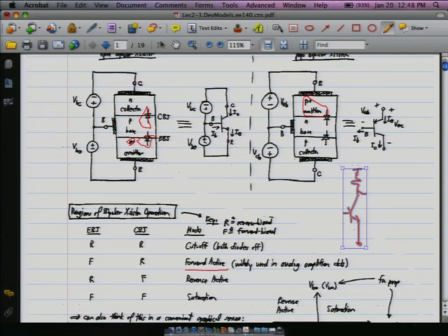And the other mode is reverse active. So basically, it's just flipped from forward active, of course. You would think that if you flip the device, you get basically the same behavior, just in the other direction. But actually, because of the doping, here we see that the emitter is heavily doped and the collector is lightly doped, what you get is a device that has very, very low gain.